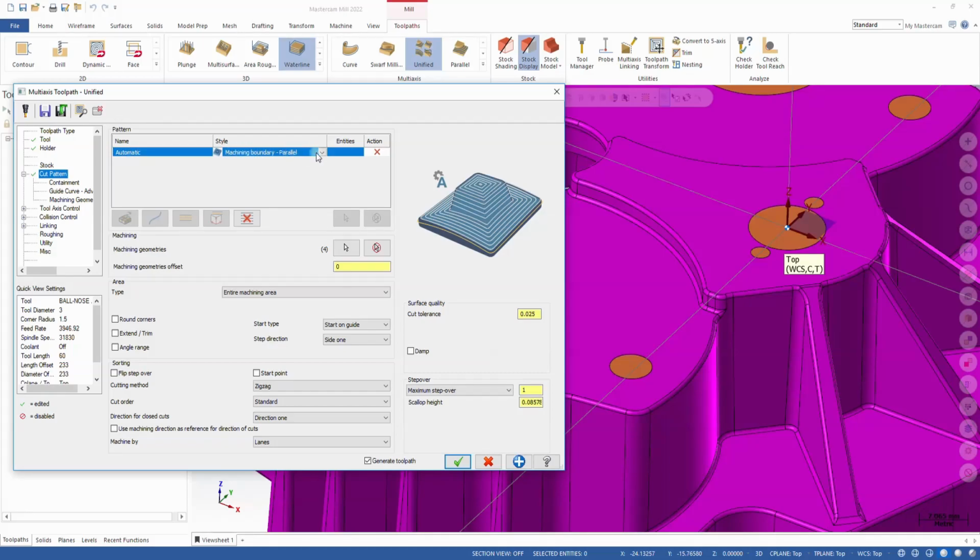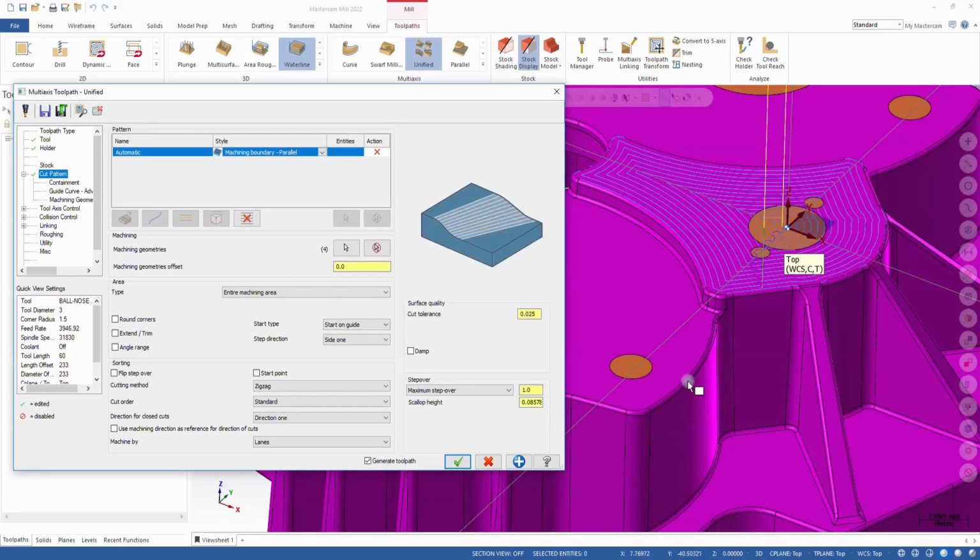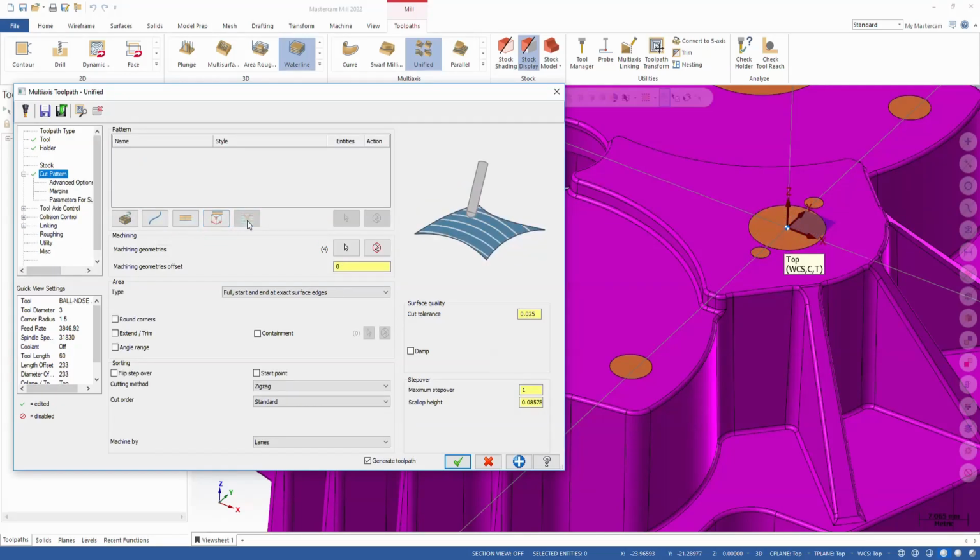But you can still have some control, and you can select different methods from morph to parallel, start inside, outside, left to right, right to left. It's really powerful. And of course you have this preview button, so you can see the results straight away, and you can change the way it's getting done. Hit the preview button and see the difference, and it's awesome. I really like it. The cross will delete all the lines, and you have different methods for manual settings.